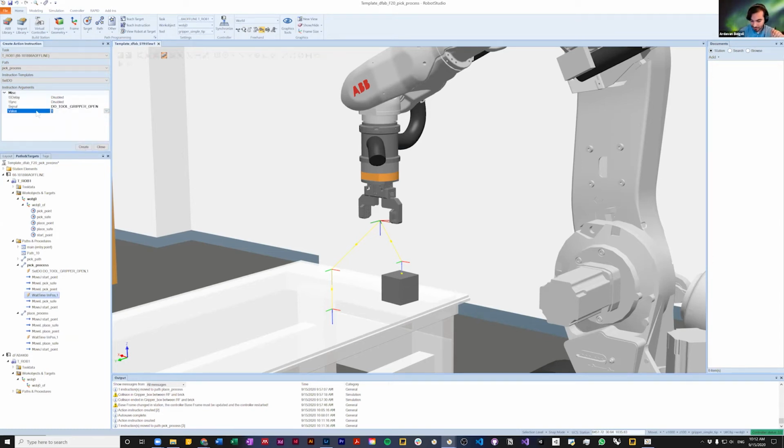And this time, I set this gripper open to 0, which means that it is not open anymore. So I hit create, and it does the job. Okay, seems legit, seems fine, but it's not done. Whenever you're using a mechanical system, it takes a second or a fraction of a second for this mechanical part to close itself, okay?